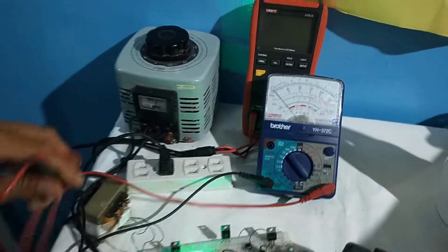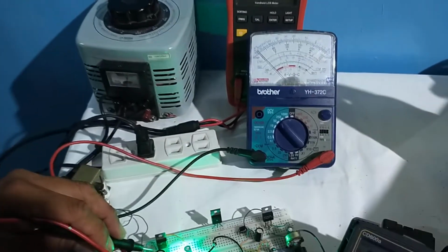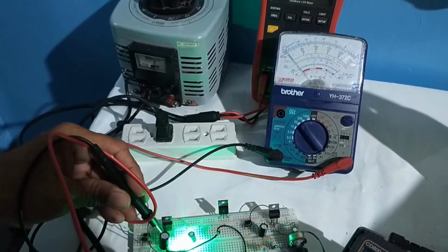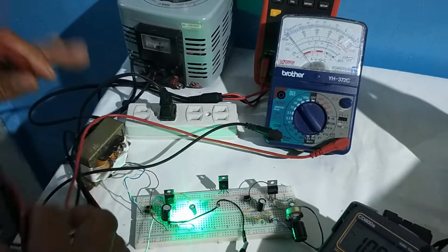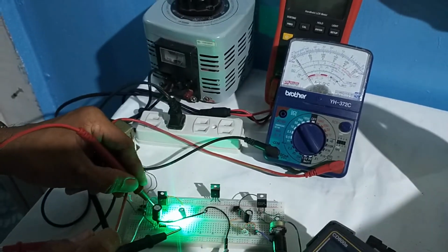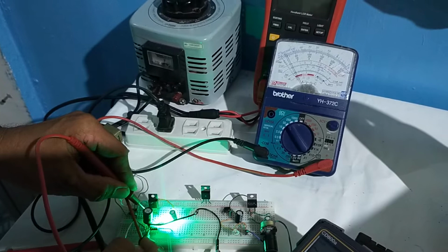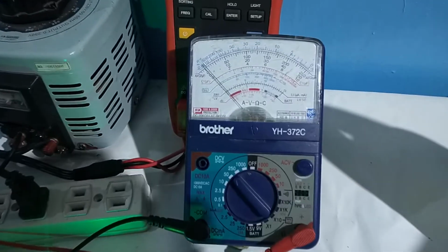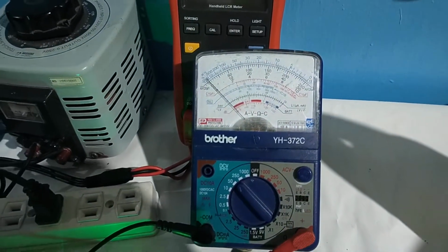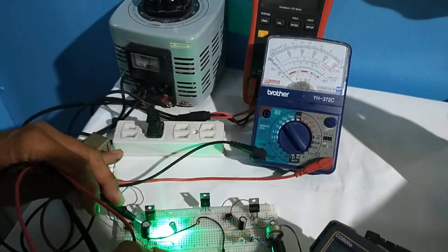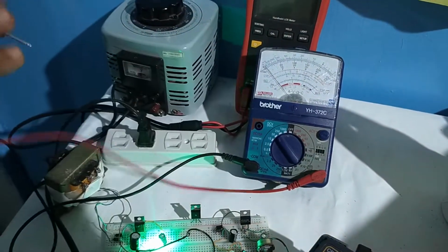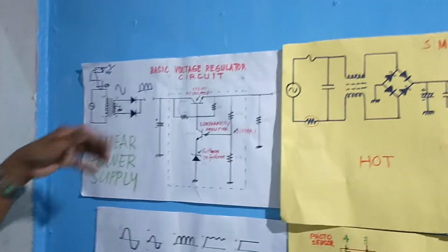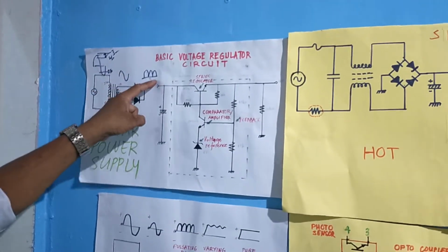But if it is reversed, it kickbacks. Meaning, it is already DC. It has fixed polarity already. Because once it is in correct polarity, the positive side is over here, and the negative side is over here, it deflects. It reaches there 16 volts. But if it is reversed, it kickbacks. Meaning to say, it has already fixed polarity, and it is DC. That is now the purpose of this diode, to rectify this AC into pulsating DC.